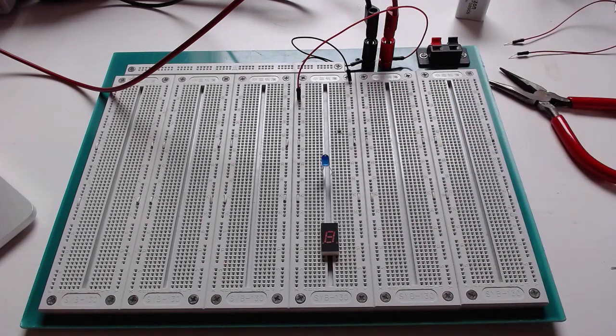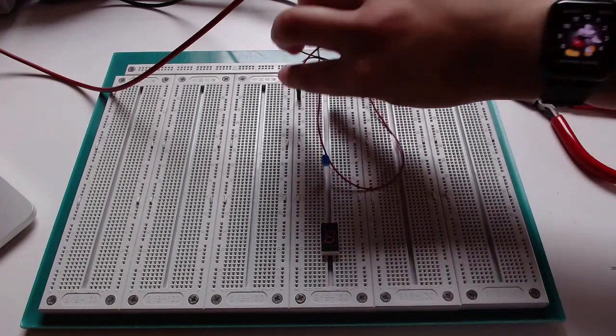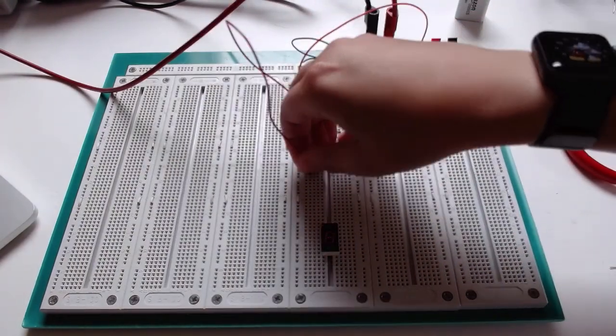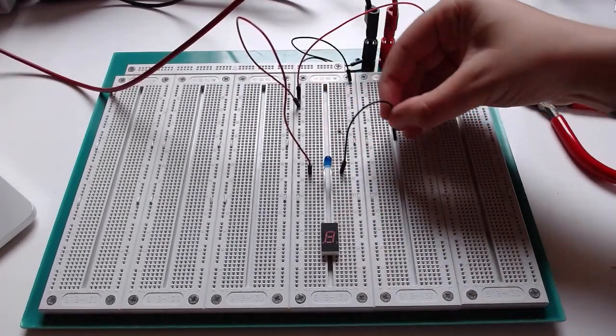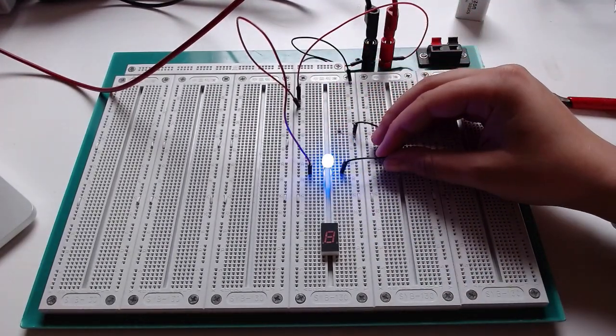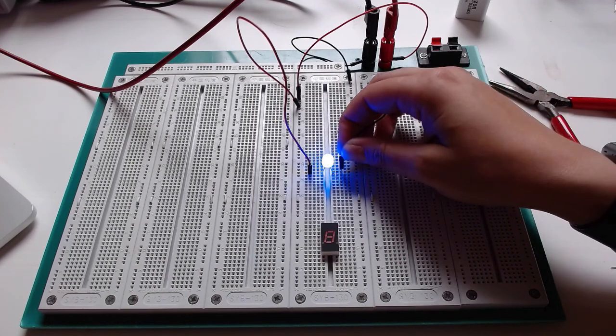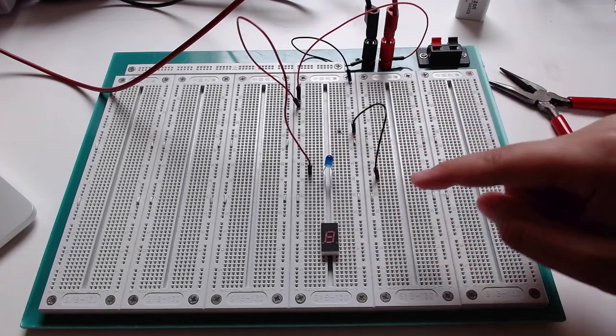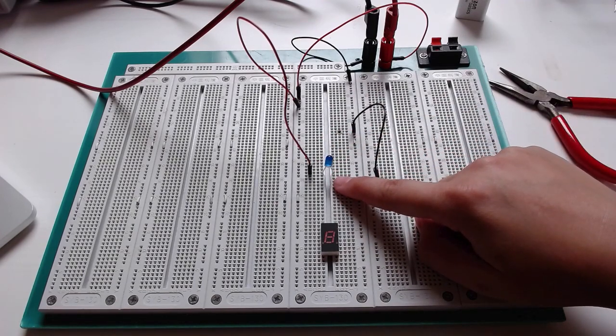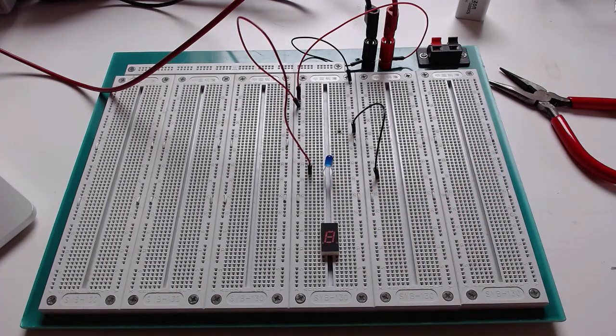Now, almost more insidious than that is having a high voltage connection that doesn't immediately smoke our LED. So I'm going to connect this LED here directly to 5 volts, and we're going to see that it's pretty happy. It's not blowing up. It's pretty bright. Now I could let that sit there for a while and it's possible that it will fail eventually. Now the worst case scenario would be that I put a lot of time and effort into soldering something like that to a printed circuit board, and over time noticing that this thing melts and it fails.